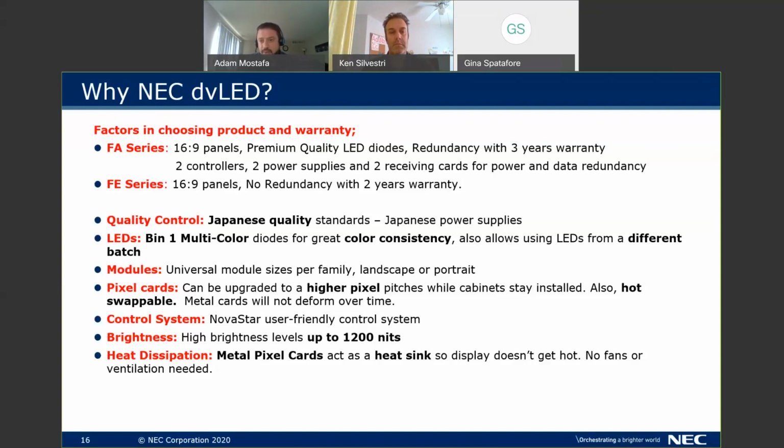I've been asked that question many times. What's the clearance that we need? Even if the wall is recessed, very minimal, just enough to let us replace that last row of panels. That's all we need. But for ventilation, we don't need any clearance.